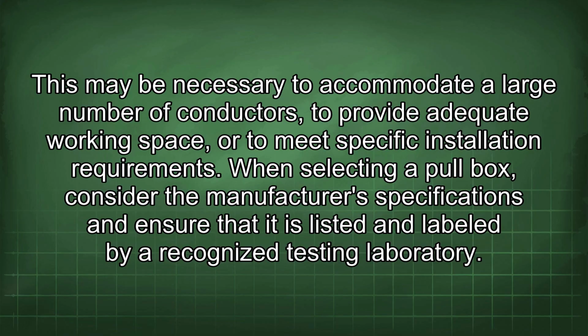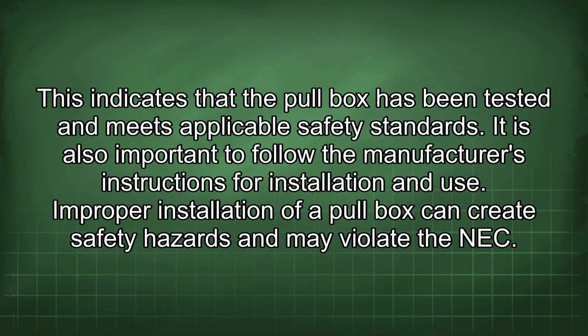When selecting a pull box, consider the manufacturer's specifications and ensure that it is listed and labeled by a recognized testing laboratory. This indicates that the pull box has been tested and meets applicable safety standards. It is also important to follow the manufacturer's instructions for installation and use. Improper installation of a pull box can create safety hazards and may violate the NEC.